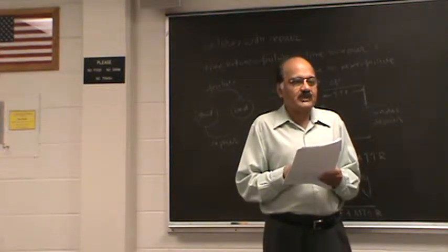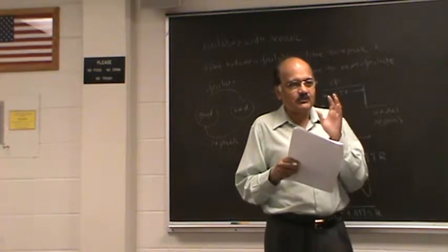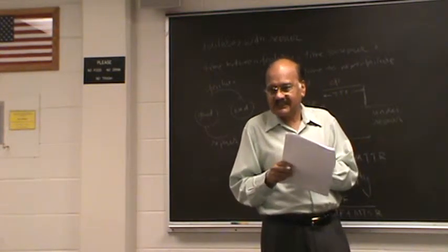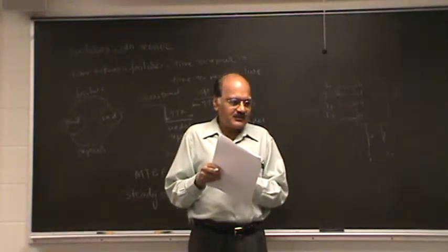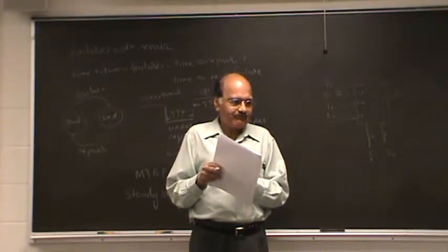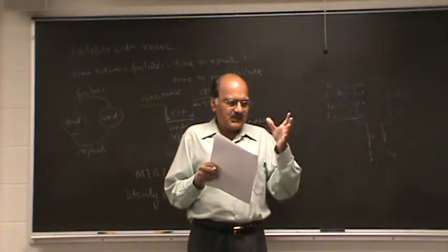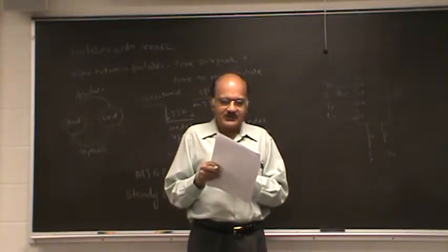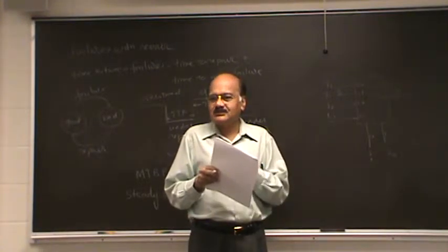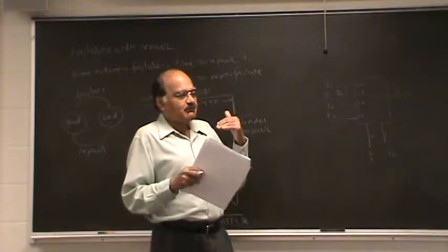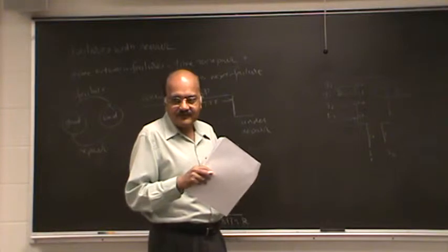But in most cases, asynchronous circuits are used only in some rather special circumstances. I think for the design of some very high-speed sequential circuits, asynchronous circuits are used, because the asynchronous circuits, they tend to be unstable. There's no synchronization mechanism, so sometimes their behavior is not predictable, so they are not used that often.